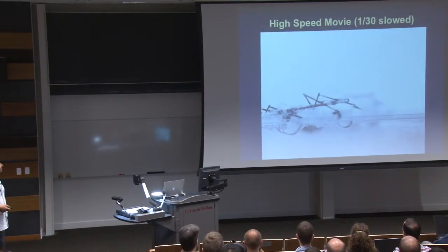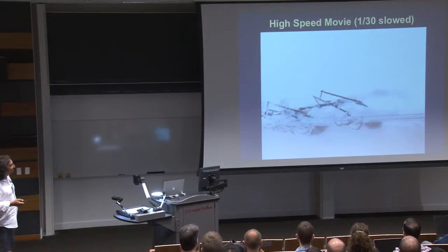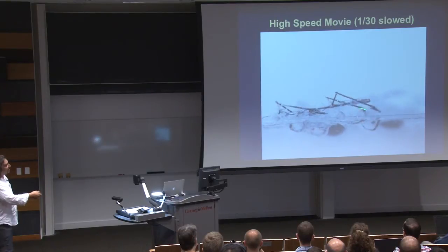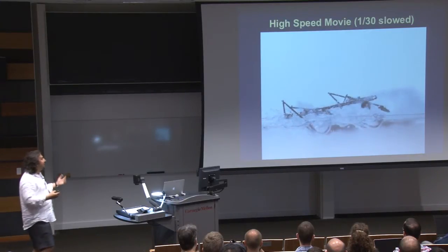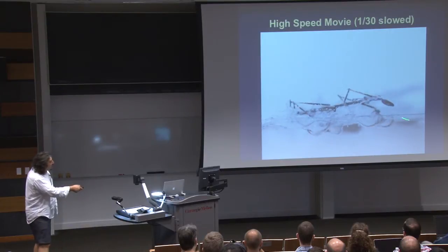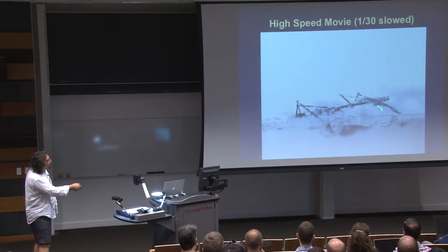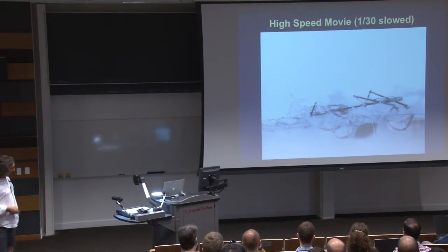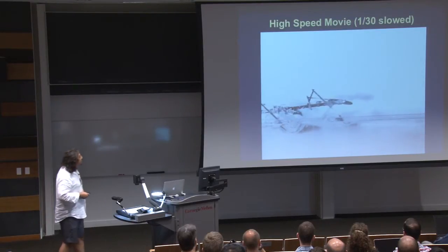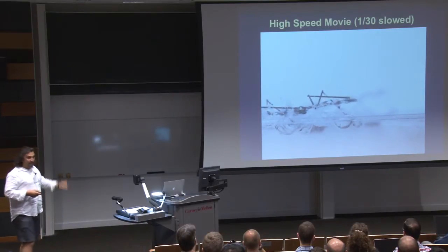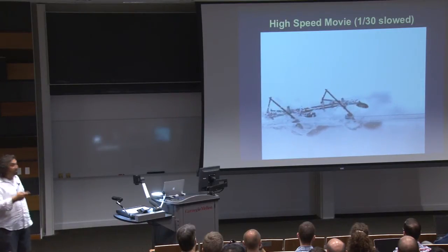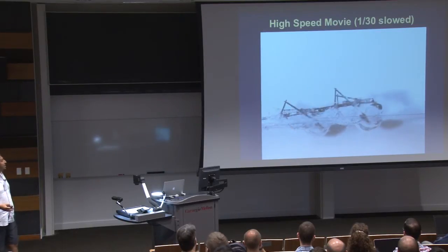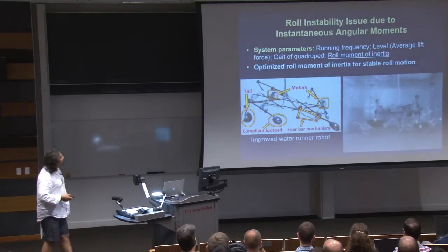I'll come to that, but before that, this is a more interesting high-speed video study to see how the foot is creating this air cavity, because in an animal we can never see in nature real videos like this. And as you see, the foot is directionally compliant, and how it folds. So we can see all these details. And in this video, there's just a tail, but no pontoon for roll stability. So that proves that this robot can lift on water like the animal, and I think it opens a new realm for legged robotic systems, operating not only on ground surfaces, but also on water surfaces.